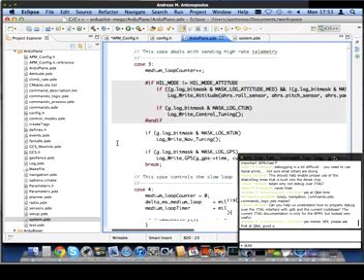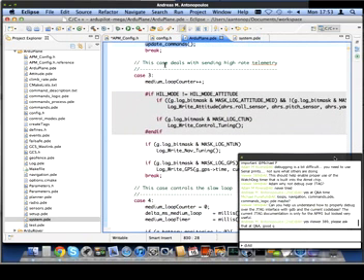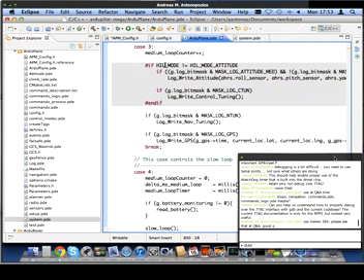Okay, then update commands there also at 10 hertz. That update commands call just above the screen there, a few lines further up. That is the call to check for the next command in our mission. So if you've loaded a mission for automatic flight where you've got a set of waypoints, then what it does is at 10 hertz it goes and checks whether you have completed the previous waypoint, ready to move on to the next one, which means it won't update the waypoint stuff at better than 10 hertz.